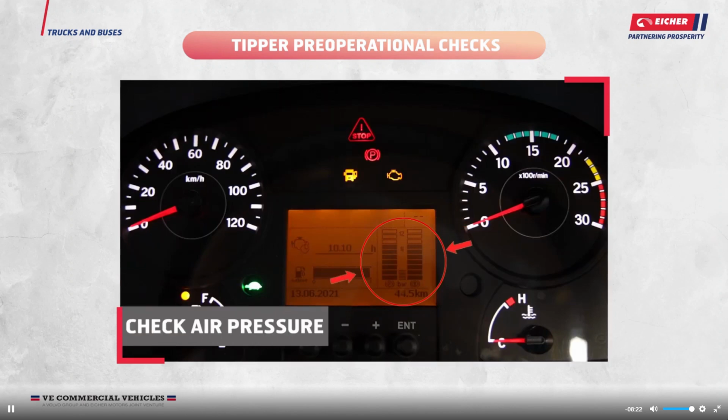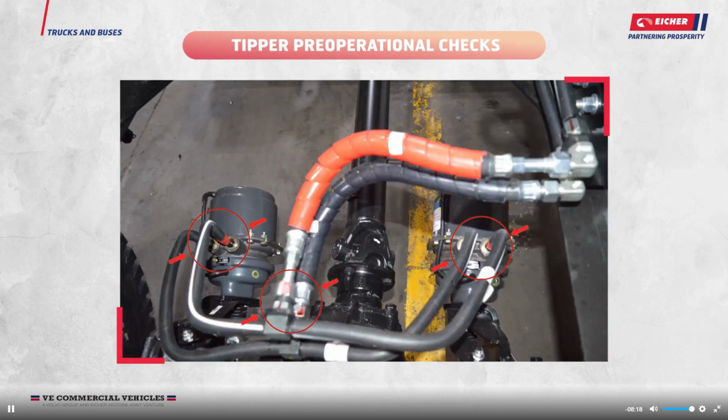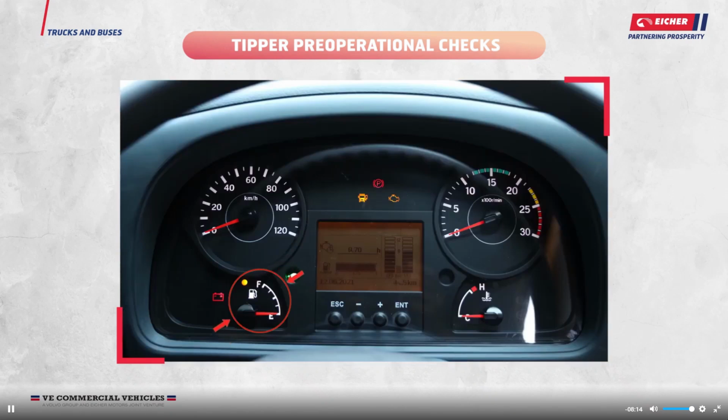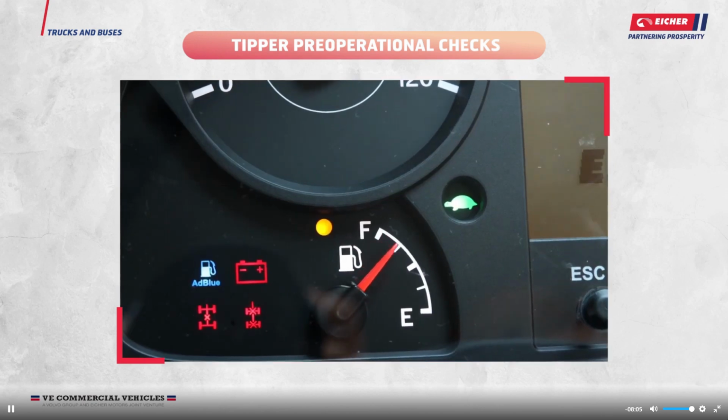Check air pressure for front and rear brakes. The pressure should be 10 bar. If less, check for air leakages and get it correct. Check the fuel level through fuel level gauge provided in instrument cluster. Note: F denotes full and E denotes empty. Fill the fuel before gauge reaches to empty position.